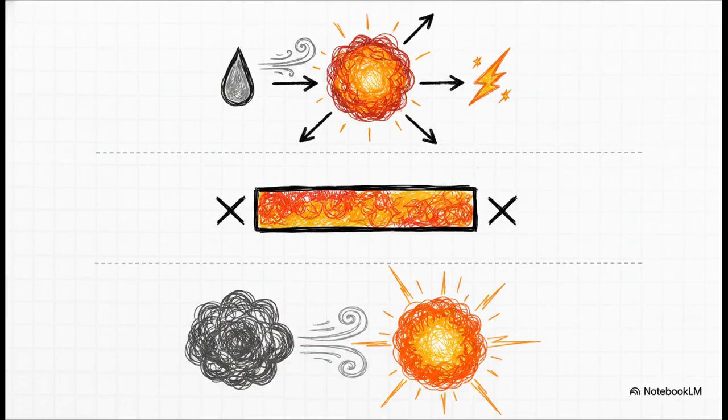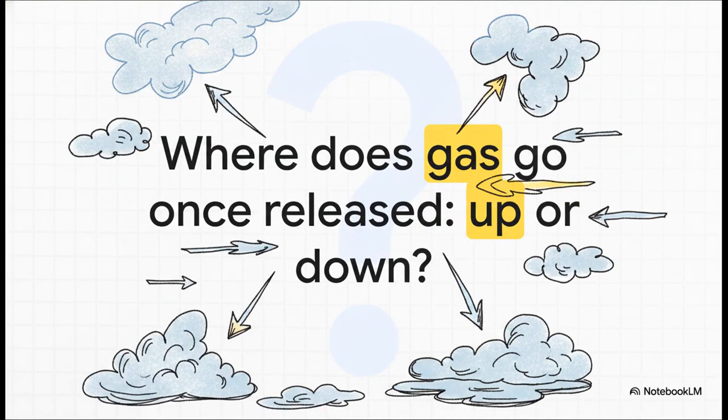Okay, let's lock in the core physics that dictate how every single piece of Ex-rated equipment is built and how every hazardous zone map is drawn. Number one, an explosion absolutely demands fuel, oxygen, and ignition simultaneously. Number two, the mixture will only ignite if it sits perfectly in that danger window between the LEL and the UEL. And number three, the ultimate trap. Never ever assume a too-rich gas is safe, because the moment it hits fresh air, it dilutes straight into a potentially catastrophic hazard.